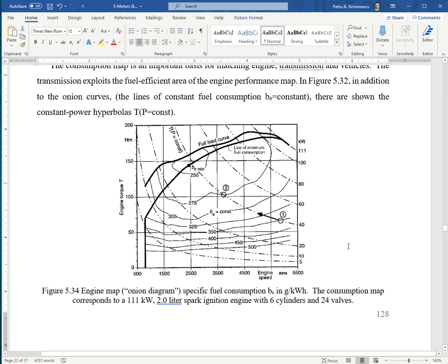And so yeah, you can have an engine with a transmission, and you can generate the desired amount of power at partial throttle, and deliver it at different RPMs by the use of a transmission. It could be a continuously variable transmission like a CVT, or a manual, multiple step transmission. And you'd like to minimize the specific fuel consumption.